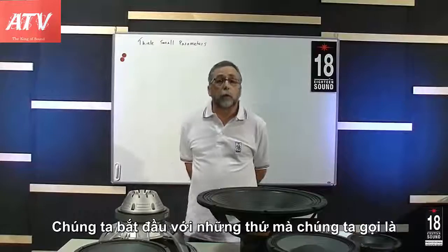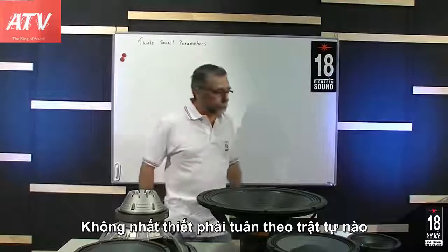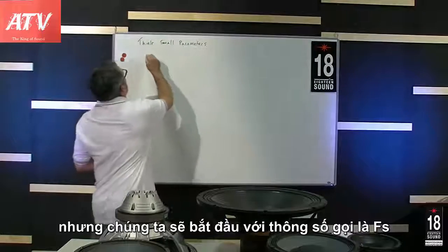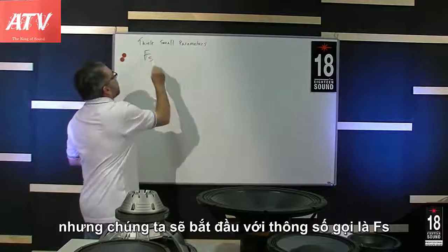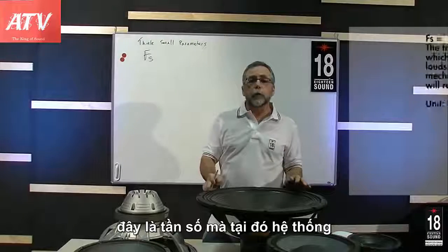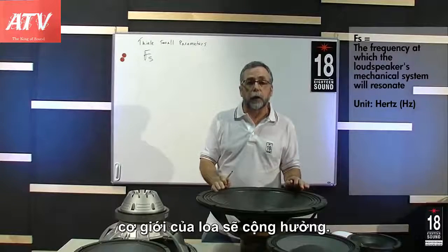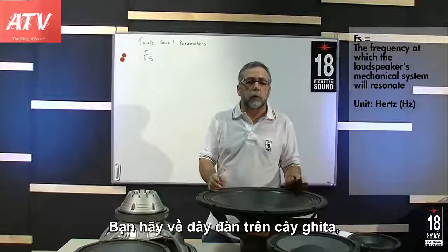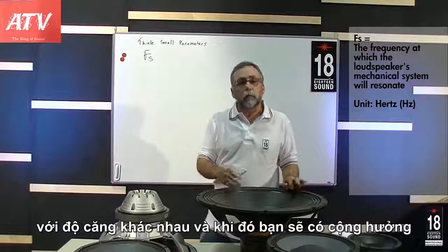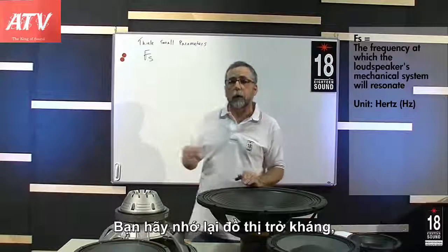So let's start with what's on the spec sheet under what we call the Thiele-Small parameters. Not in any specific order, but we'll start with what we call FS, the resonance frequency. This is the frequency at which the loudspeaker mechanical system will resonate. If you just think of the string on a guitar, the different size strings and the different tension, you have a resonance. And this is what we're referring to with the loudspeaker.